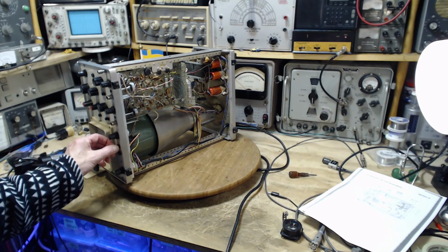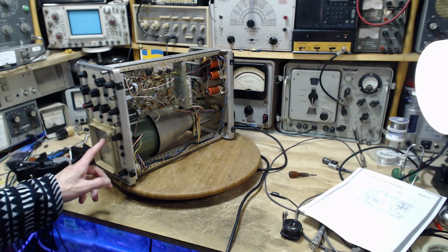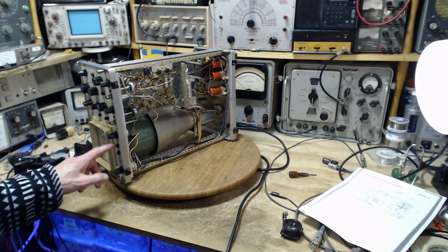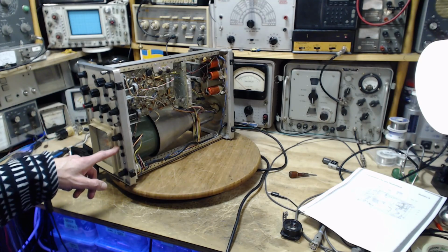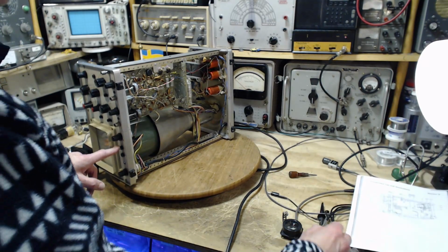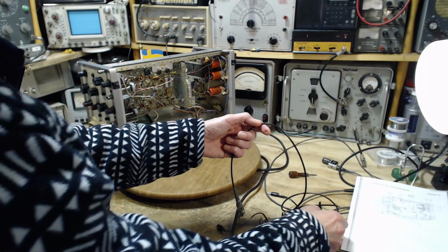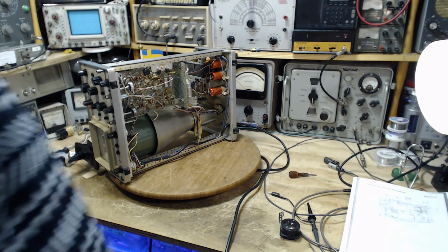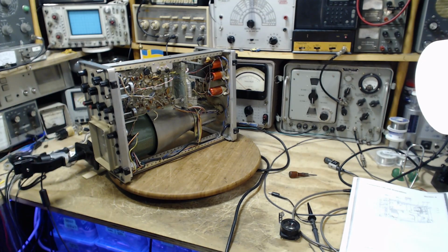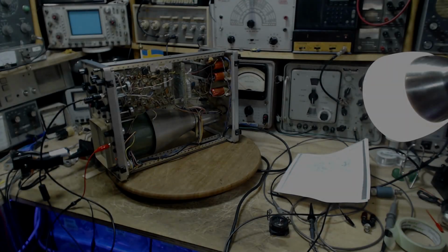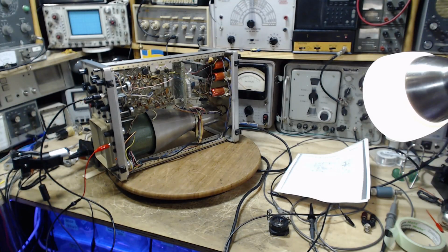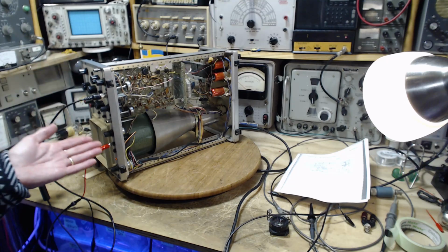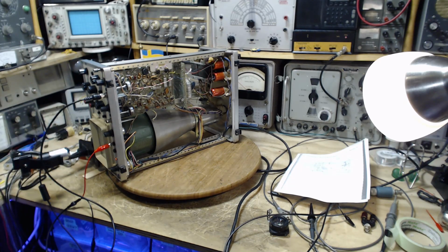So what am I to do here? I think what I'll do is I'll check the calibration as it exists right now using this 1 volt supply. My earlier impression is that it will show up a little too large. Well, let me just get that going, and we'll see. Okay, so trying to do this with a calibrated 1 volt source, and when I don't have one, well, what am I going to do? First, I'm going to start by using the source that's right on the scope. And we'll take a look at it.